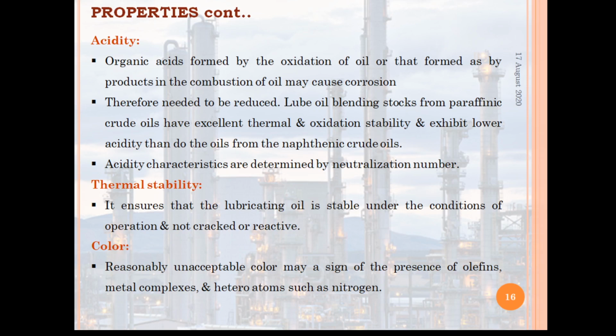These come from the solvent extraction process: after propane deasphalting, in the solvent extraction process, we get the paraffinic one as a top product. These lube oil blending stocks from paraffinic crude oils have excellent thermal and oxidation stability, and exhibit lower acidity than the oils from naphthenic crude oils.